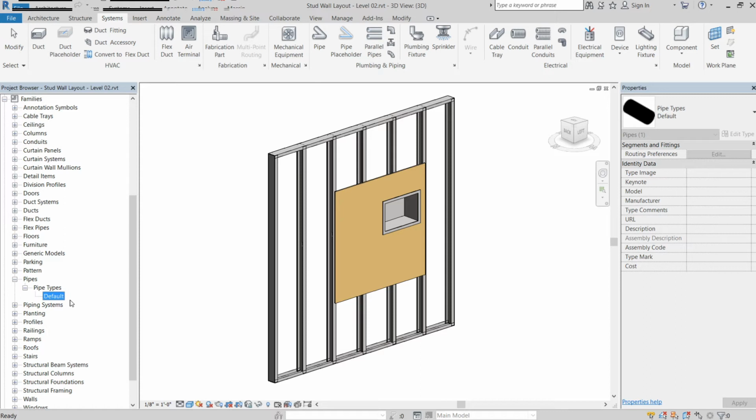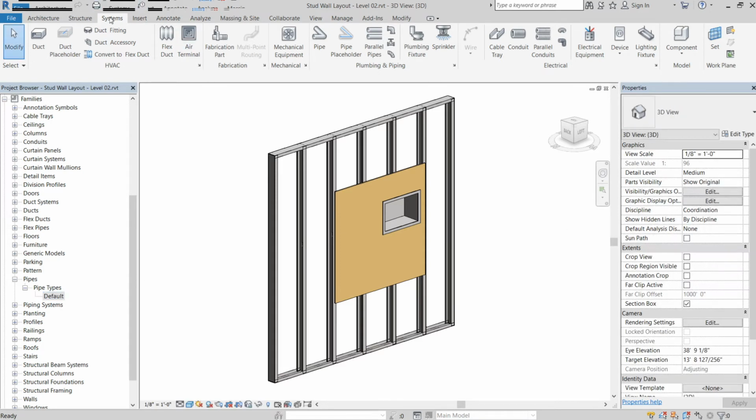So the way Revit likes to operate is it wants you to just draw lines, and it wants to automatically put fittings on those pipes for you. So anything for Ys, for your traps, for your 90s, everything. And you can go into, we're actually gonna have to insert these.